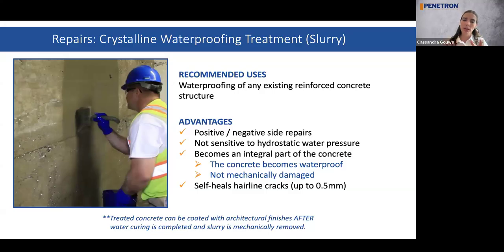Now, even though it's applied on the surface, it's not a coating. It's just a treatment. So if you would want to remove it or paint your structure after the fact, you would have to cure it with water for 14 days. Now, after the 14 days, you can actually remove it, mechanically remove it, because enough active ingredients would have gone into your concrete to grow those crystals for the lifetime of that concrete.